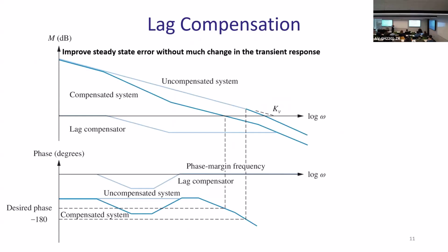All right. So the idea of lag is, again, don't touch the phase at all. Try to use that controller somewhere outside of the range of the change for the phase margin. Like wherever your phase desired angle is there, don't touch that region, don't modify phase in that neighborhood at all. Don't touch it. Do it somewhere to the left from that point.